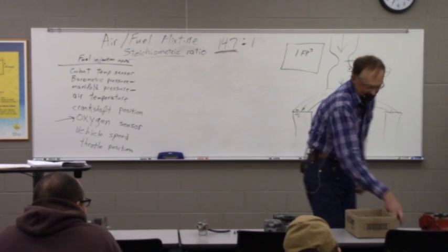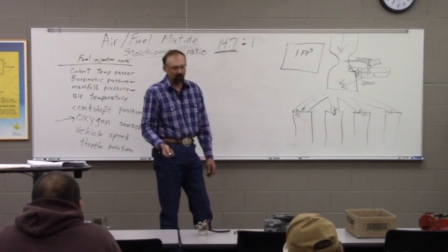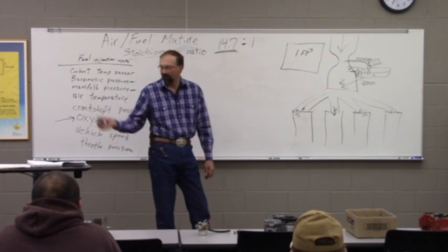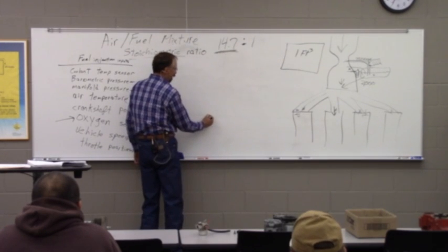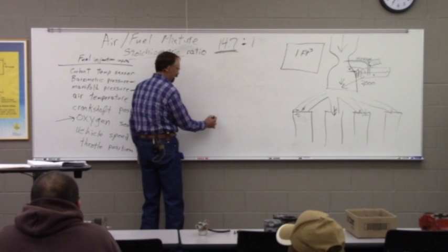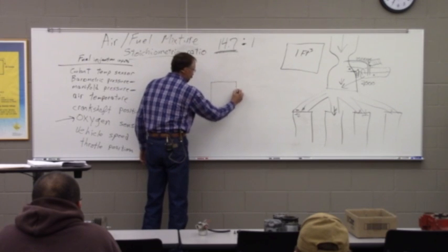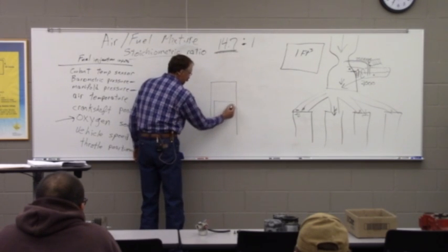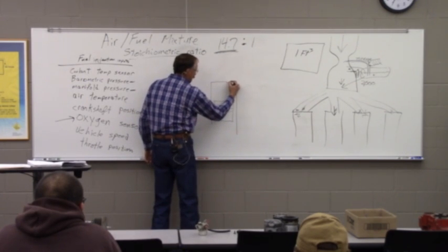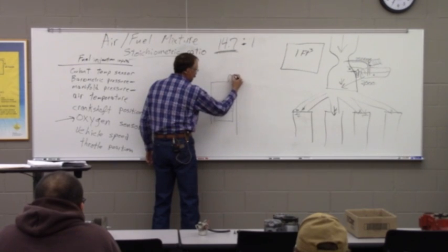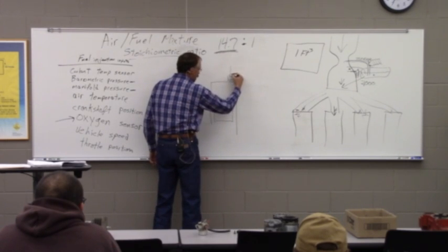An interesting side note, I was looking at some of these books from when I was in automotive school, and a few things have changed. That was in the real early 90s, and diesel engines at that time were mostly what are known as pre-combustion chamber engines, or PC engines. So if this was your cylinder, your piston sits in here, of course. What they would have is, typically off to one side, a little chamber like this, and the injector would spray the fuel right in here.